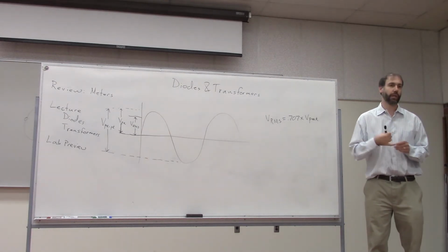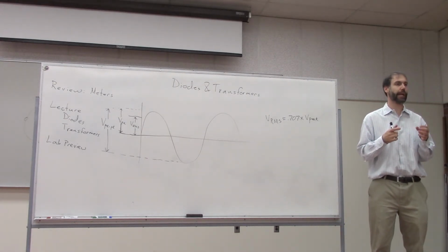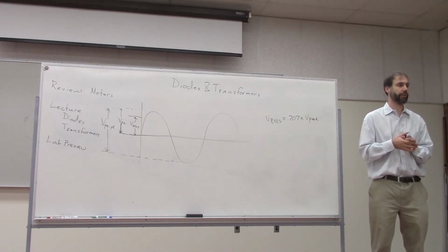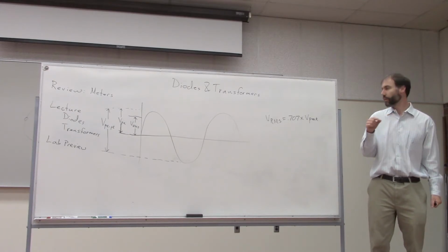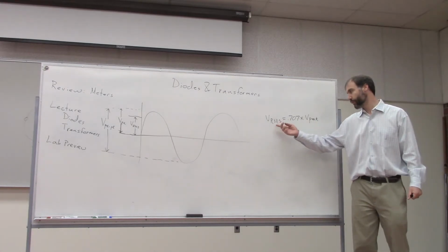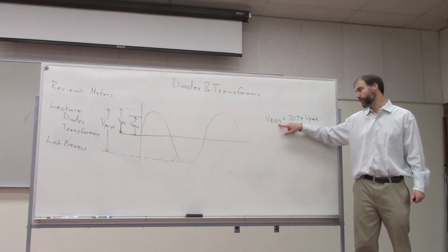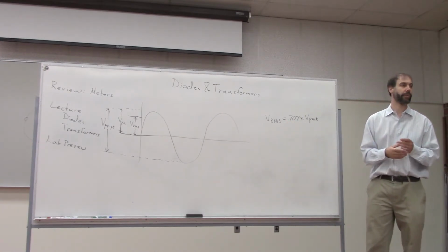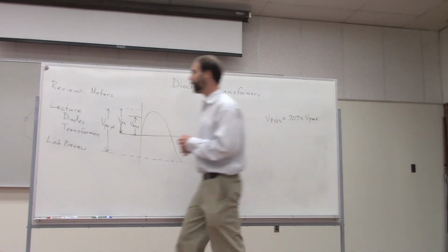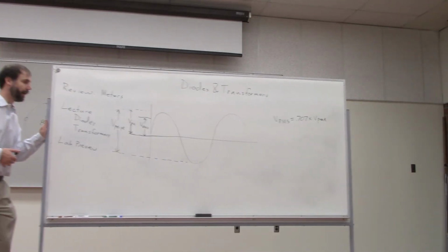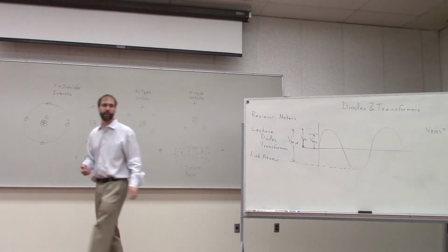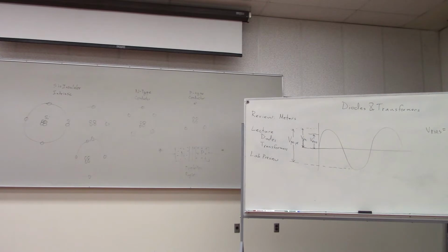That's true with the meters that we have in the lab. That's true with the meters in Multisim. It's true with almost any digital multimeter that you use, unless it specifically says a different voltage. The voltage that it's showing you for AC signals is in RMS. Okay? All right, so with that said, let's talk a little bit about today's lab. Any questions before I go on? All right, then let's talk about the lab for a few minutes.